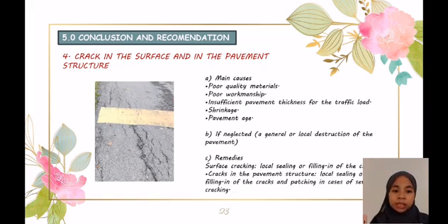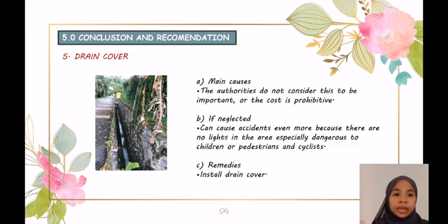C, remedies. First, surface cracking: local sealing or filling in of the cracks. Second, cracks in the pavement structure: local sealing or filling in of the cracks and patching in case of severe cracking. Fifth is drain cover.